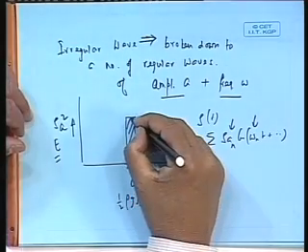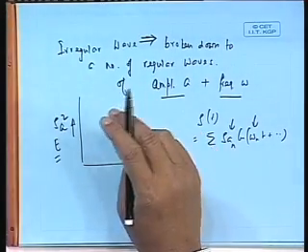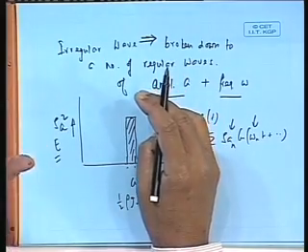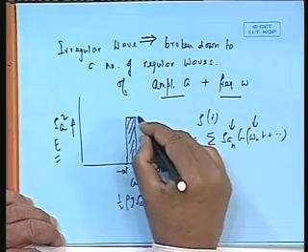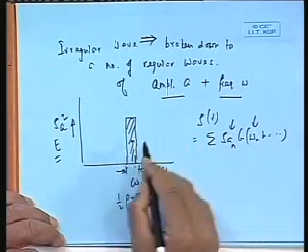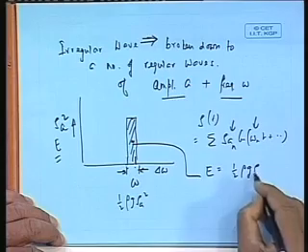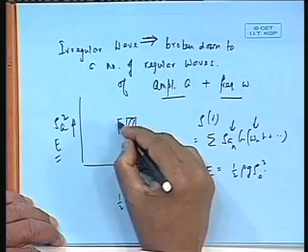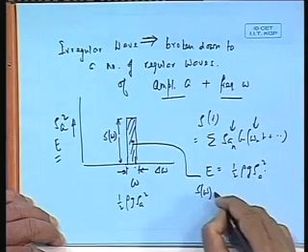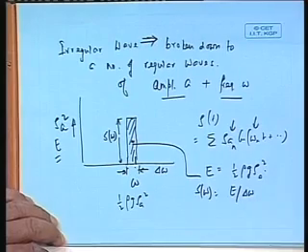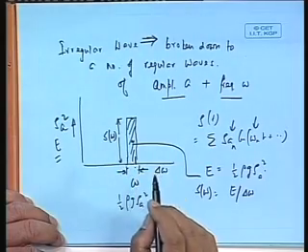That would imply that this is my energy. If you make such a plot, on the vertical side you take amplitude square divided by, see, I call this delta omega. So if this shaded area has to be the energy equal to half rho g sum of a square, then this height, it is called S(omega). S(omega) then becomes E divided by delta omega, because I have taken delta omega to be this distance.